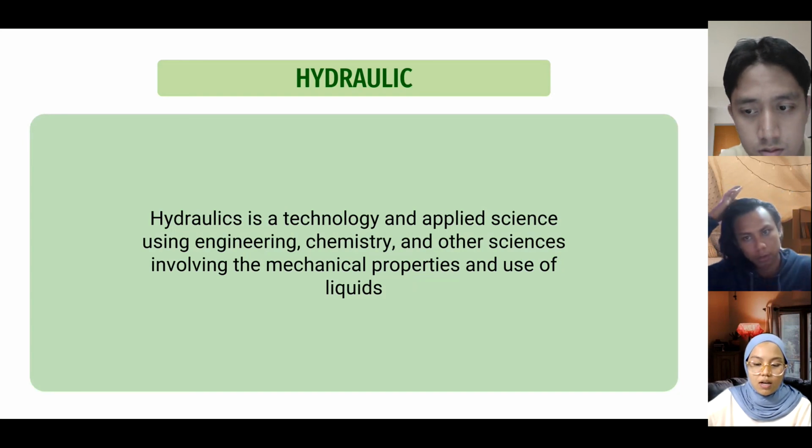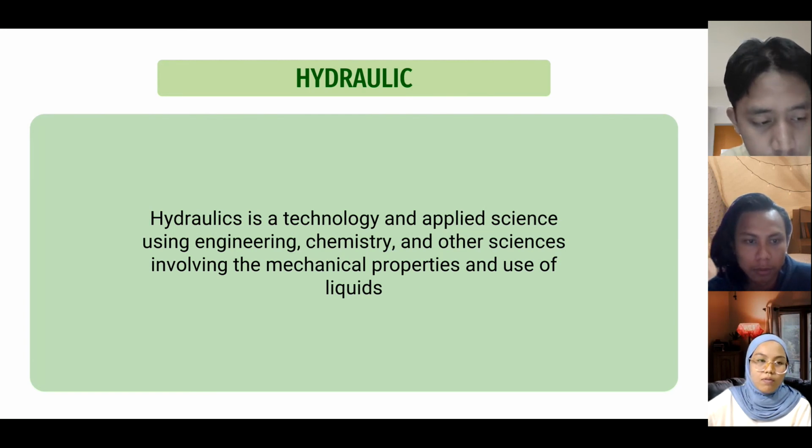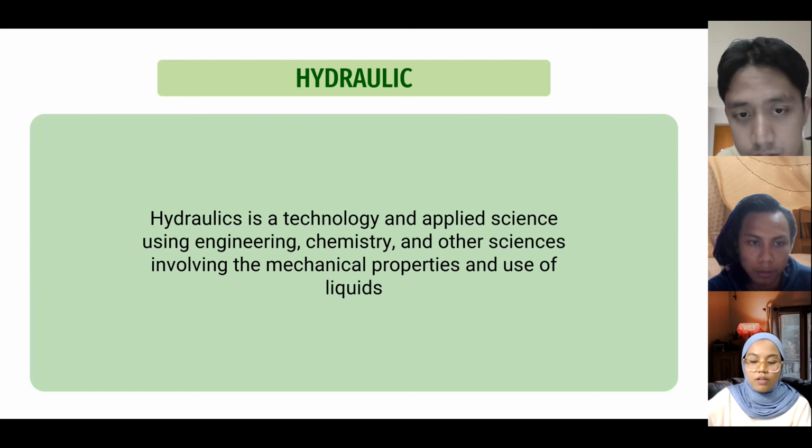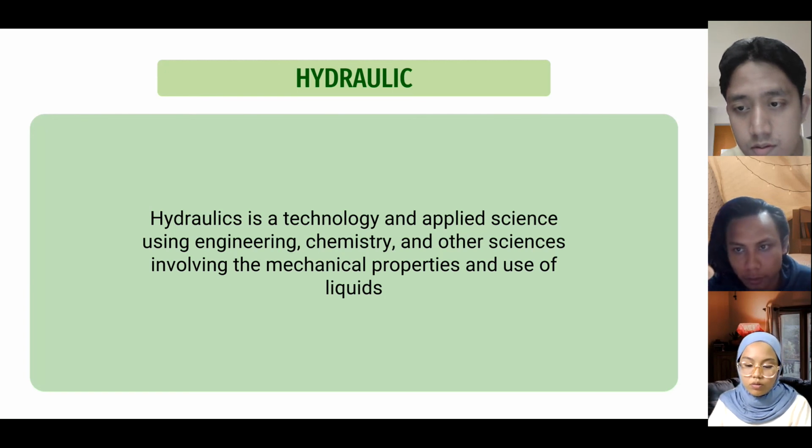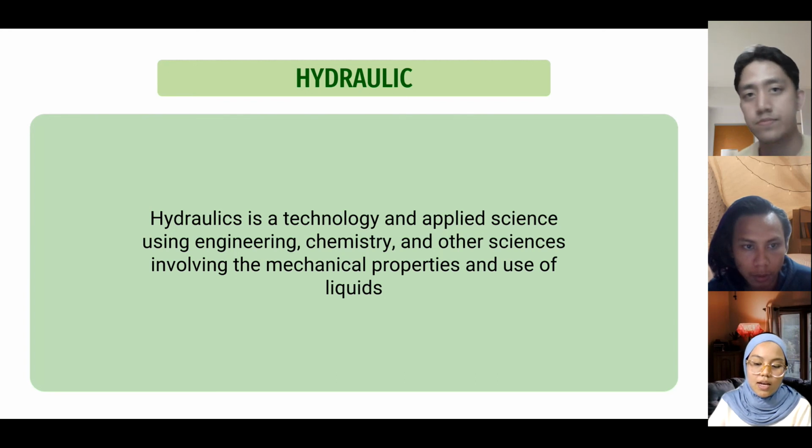Hydraulics means the use of pressure to generate, regulate and transmit power. It is a type of technology and applied science that deals with the mechanical characteristics and the utilization of liquid. Hydraulic systems, like pneumatic systems, require a pump and employ valves to regulate the force and velocity of the actuators. In hydraulic applications in industry, pressure ranges from 100 to 500 psi, with pressure exceeding 10,000 psi used for specialized applications.